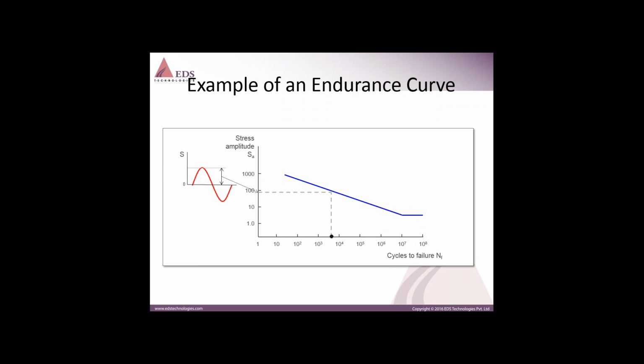Let us consider one stress amplitude. Earlier, when we were using the SN type of approach, we were calculating the stress amplitude, plotting the corresponding stress amplitude on the y-axis, and drawing a line, and the corresponding point on the horizontal axis is where we claim that our life is this many cycles.